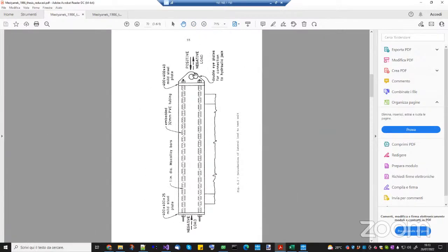Okay, so basically here on the right-hand side, they applied both positive and negative load. Now, a positive load is actually pushing, but the negative load, if you apply it directly in the finite element model, you actually will be pulling the wall, which is not correct. Actually, what you want to do is to pull here this plate, but it will apply a positive pressure on the other side.